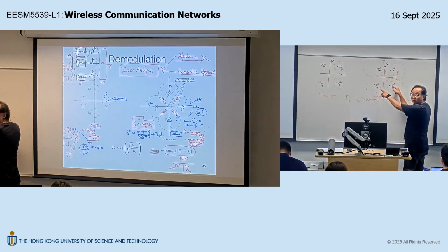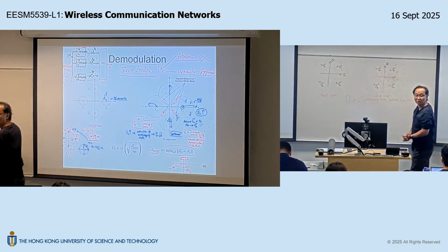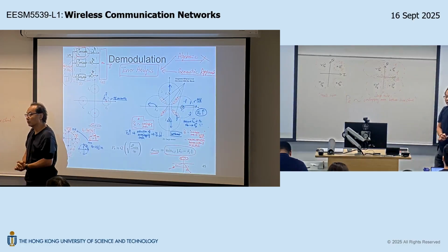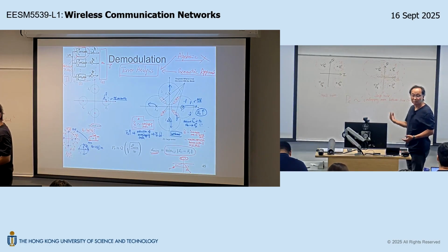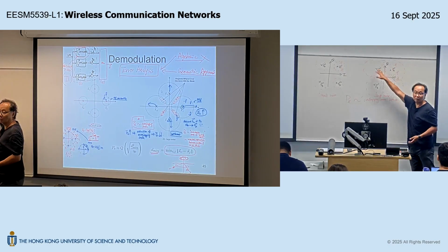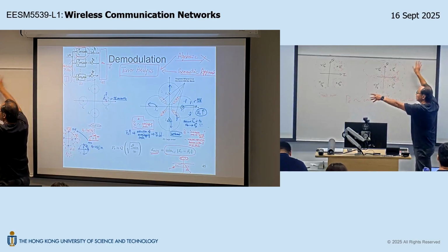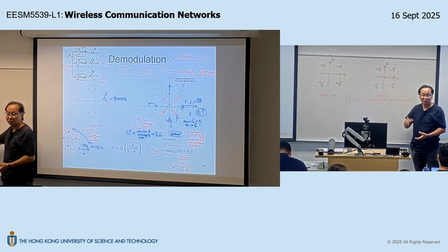The center is something you can design, right? If you can pull the noise clouds further away, then you can reduce the overlapping area and therefore reduce the error probability. Can you see that? Okay, but what exactly do we mean by moving the center away? We have to increase the transmit energy. Can you see that?